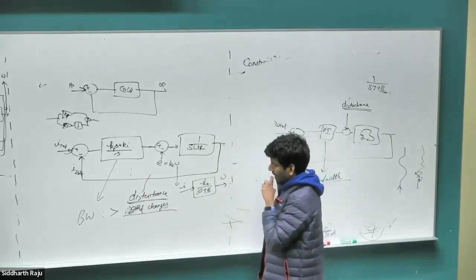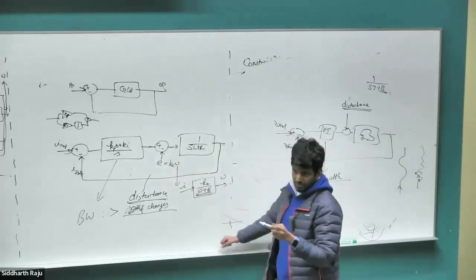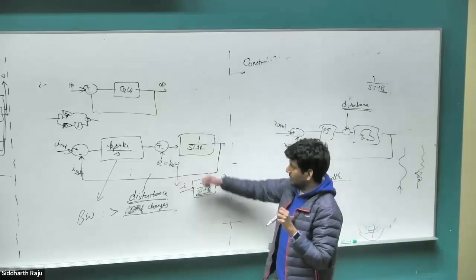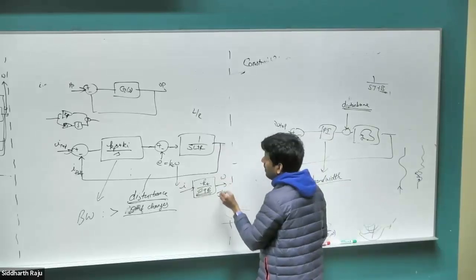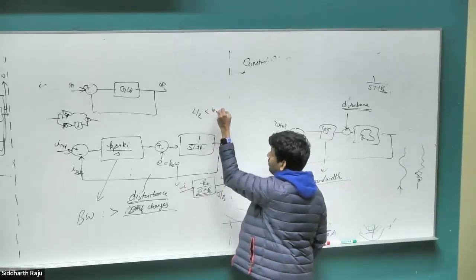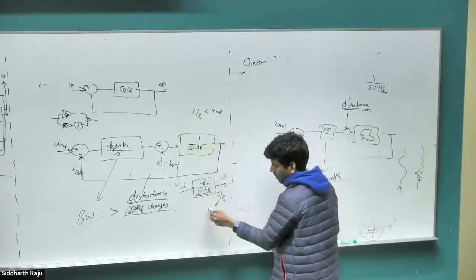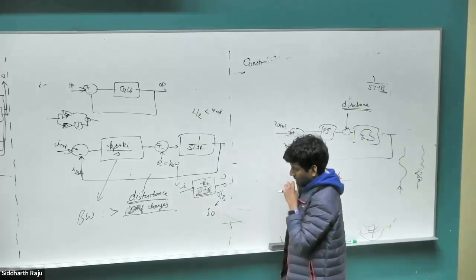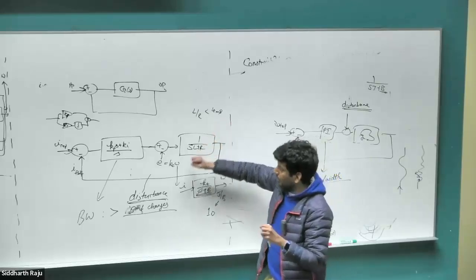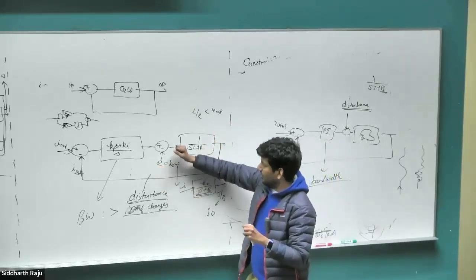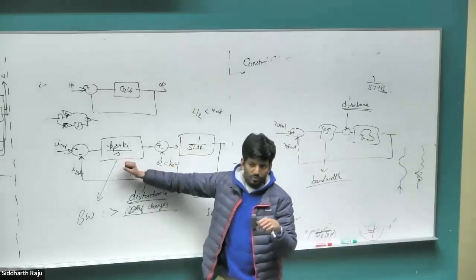Right? So the rate at which our EMF is going to change for any changes in the current is going to be dictated by the time constant of the mechanical system. But the rate at which our electrical system responds is determined by the time constant of our electrical system, L by R versus J by B. As you all saw on the homework, L by R was 4 milliseconds, I think. J by B, I think, was 1 second or 0.4 seconds or something. So at least on the order of 100 to 1000 times larger. So it's absolutely fine ignoring this EMF, because we know that for a change in the current, the EMF will change so slowly that our control system will be able to adapt to it, which is no problem at all.